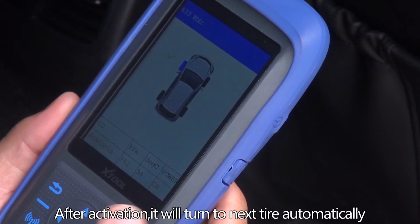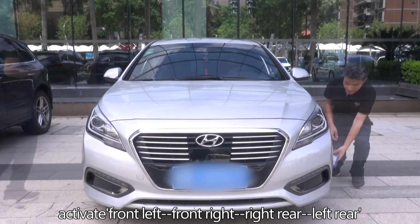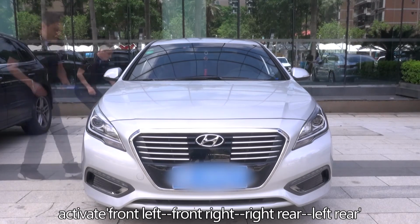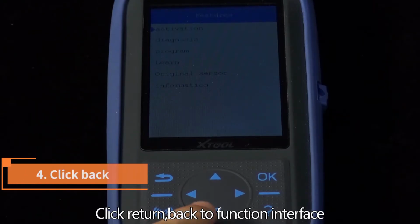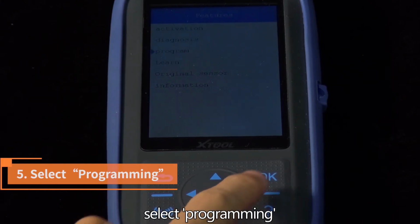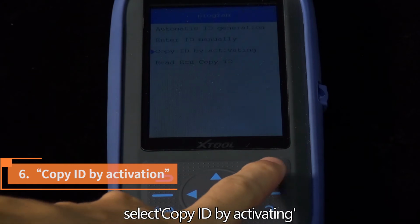After activation, it will turn to the next tire automatically. Activate front left, front right, right rear, left rear. Click Return back to function interface. Select Programming. Select Copy ID by activating.